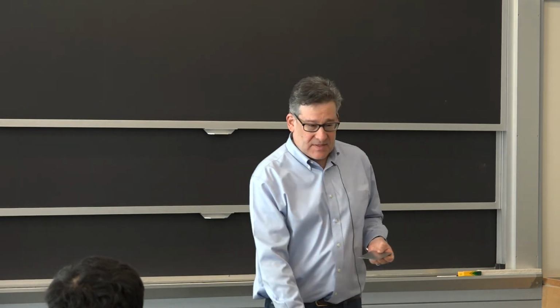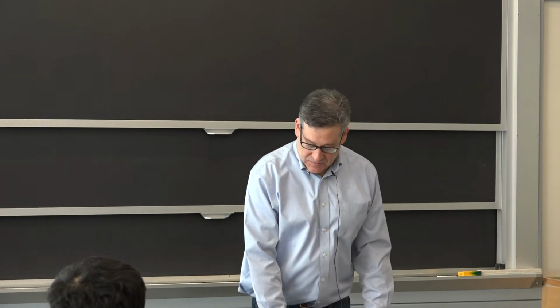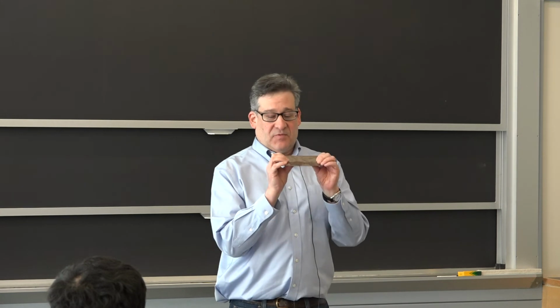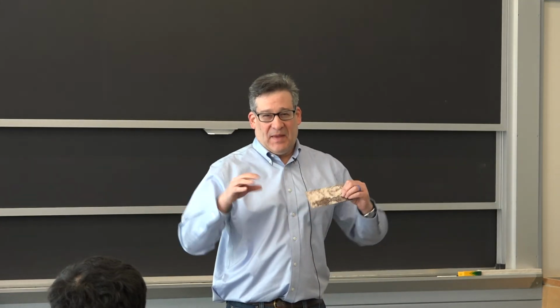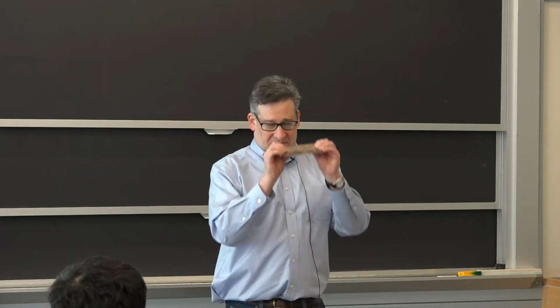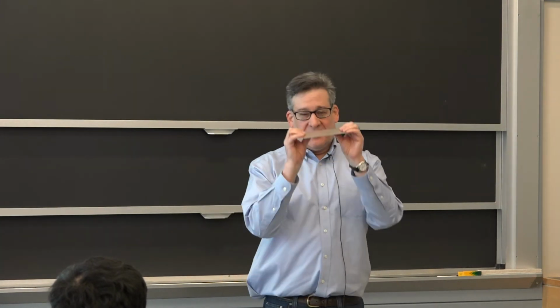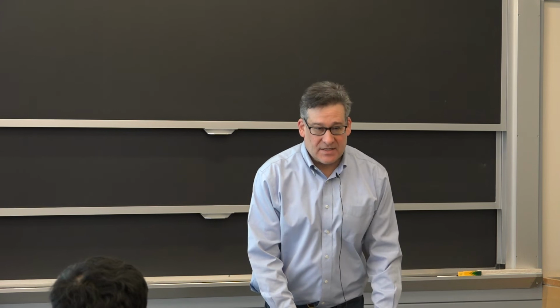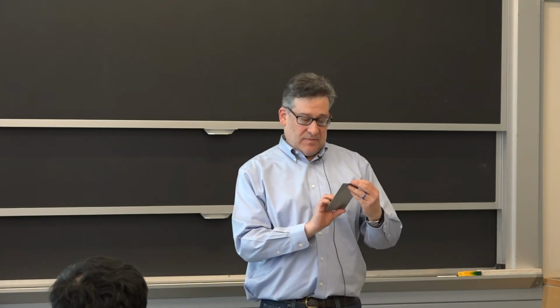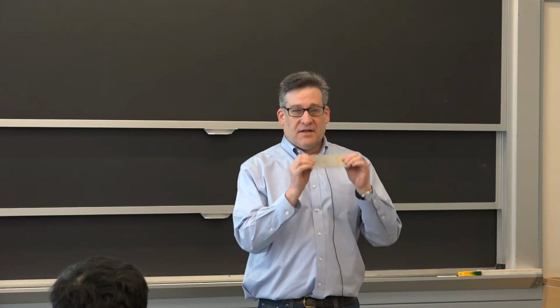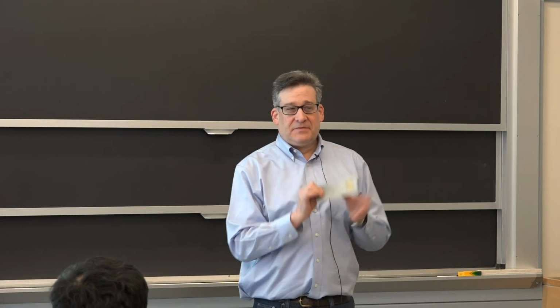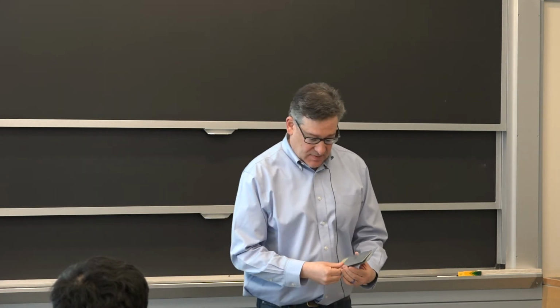And what I'm going to do is send these around the room, and I want you to try to bend them. Don't yield them. Don't bend them past the point where they're going to fail, but just flex them a little bit. And I want you to feel how stiff these are. Okay, and you're going to see that when you get to the aluminum reinforced with aluminum oxide fibers, it's incredibly stiffer. So I'm going to pass these around and try to keep them in order.